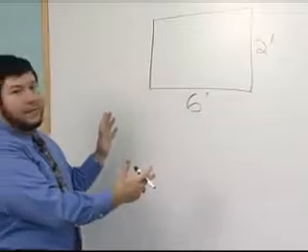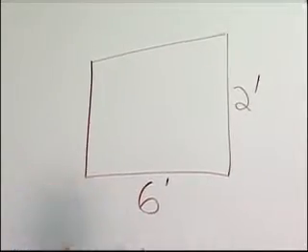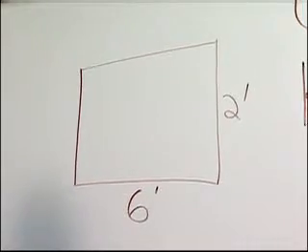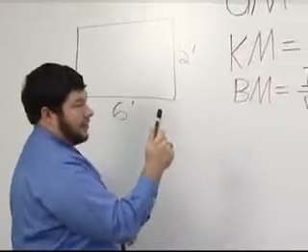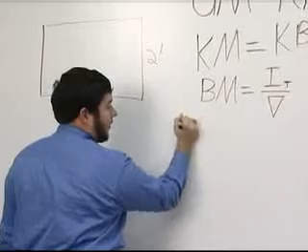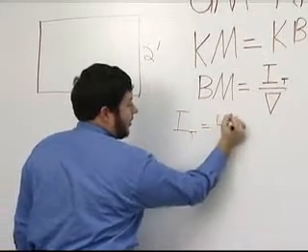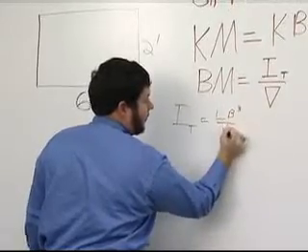Now, using the box barge example that we've used before, looking down on a plan view, the length of the barge is 6 feet and the beam is 2 feet. And for a rectangle, the equation for the transverse moment of inertia of the water plane is length times beam cubed over 12.